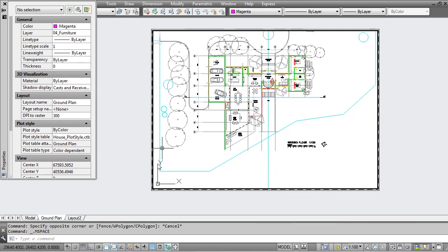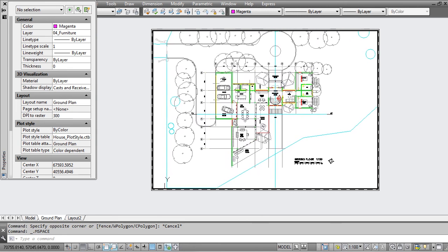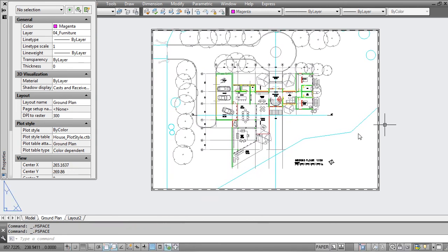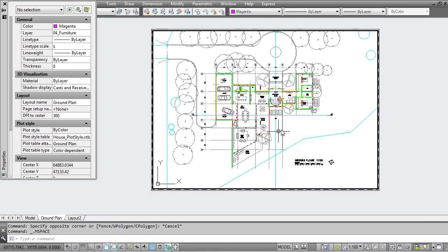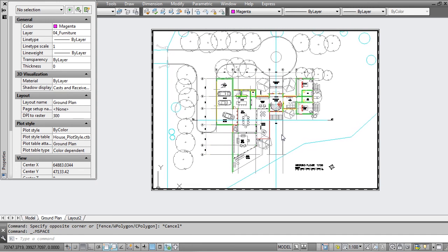It's not necessary to have 100% of the site in the window, since you would generally want to have a site layout plan, which is going to be a completely separate plan, perhaps at 1:500, where you just show the outline of the roof and then you focus on the landscaping and some of the surrounding contours. So for our purposes, we are going to let this be our layout.